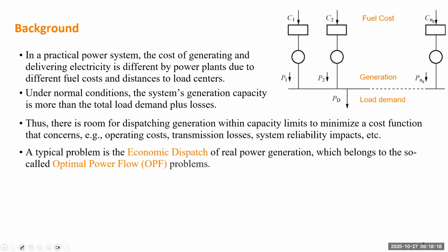You solve the other two, and you create the same number of equations as the unknowns, right? So for each bus, based on Kirchhoff's current law, you create one complex equation that gives you two real equations to solve the two real unknowns at each bus. And finally, you find only one solution. So that's the power flow problem.